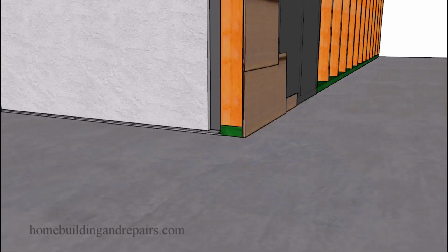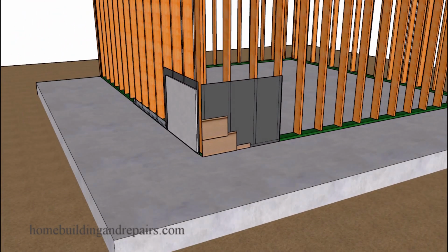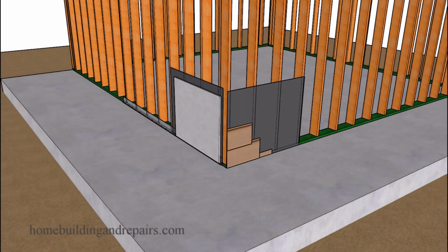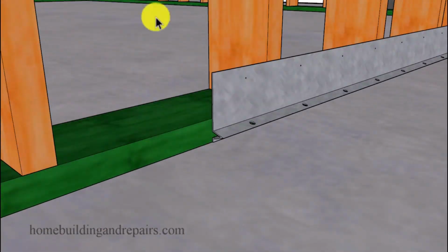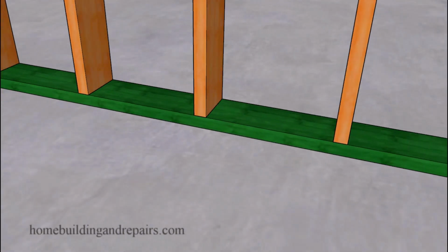And of course, here is where the problem is going to go from bad to worse, by building a smaller building on top of a wider or larger concrete foundation that might also be an existing foundation, and not dropping the concrete down so that the standing water that sits on top of the concrete won't be able to flow in through any crack or crevice here and into the building where you might have a nice piece of carpeting or a natural wood floor that is going to get ruined.